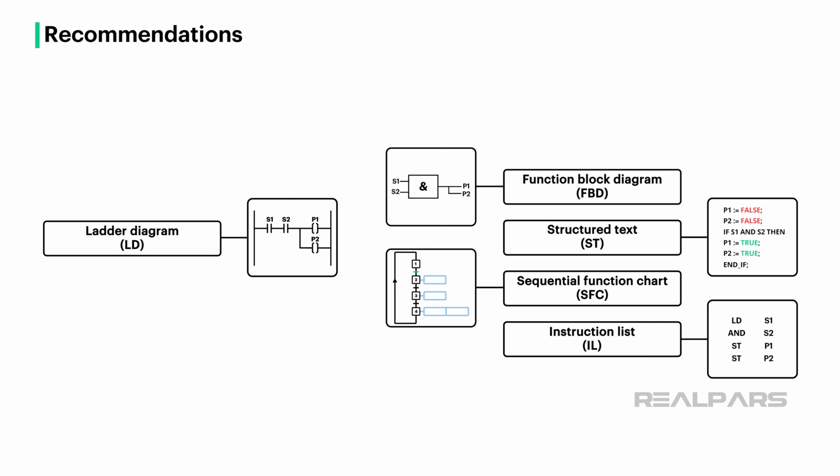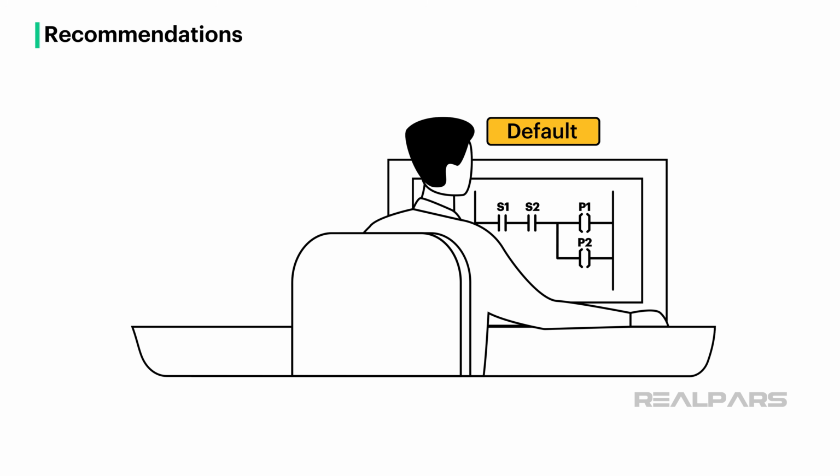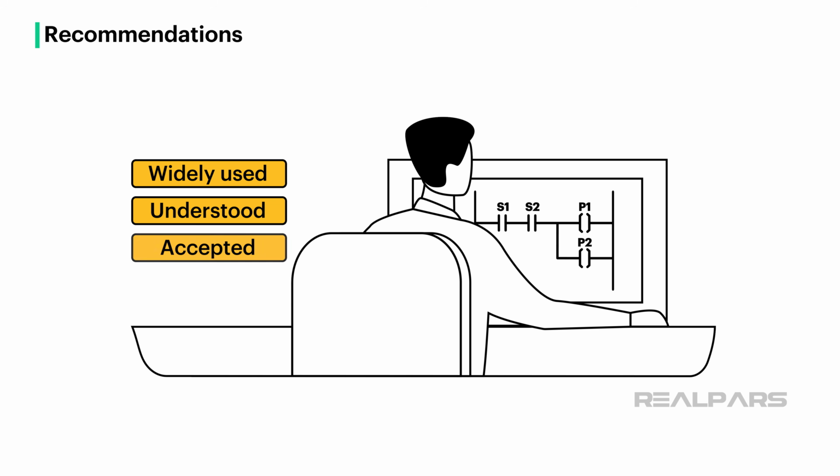Now that we have compared all of the IEC 61131-3 programming languages to ladder diagram, I would like to make a few recommendations for which programming languages you use in your everyday work. First, I recommend that every PLC programmer learns how to program with the ladder diagram programming language and uses it as their default programming language. I make this recommendation because ladder diagram is the most widely used, understood, and accepted PLC programming language right now.